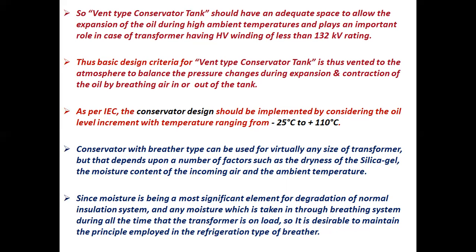Since moisture is the most significant element in the degradation of a normal insulation system, any moisture is taken in through the breathing system during all the time that the transformer is on load. So it is desirable to maintain the principle employed in the refrigeration type of breather.